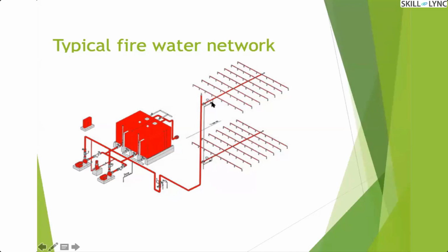So what you have to do is solve for each of these points. You should also meet the required flow rate at the furthest nozzle. You should be able to calculate the entire system flow rate. When your flow is only happening till this point, then the pressure at this point will be different.